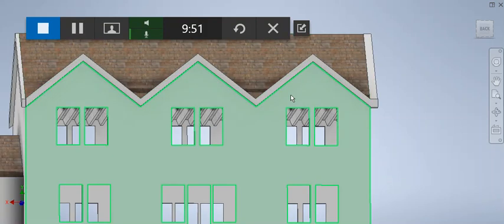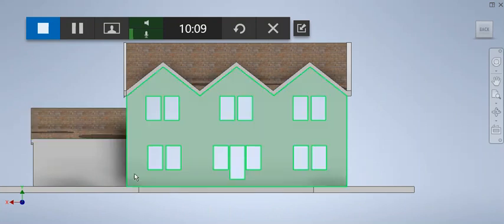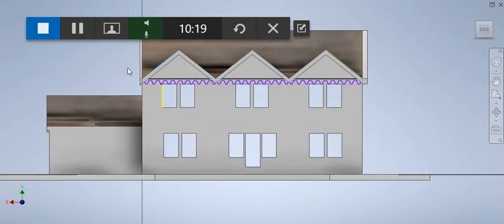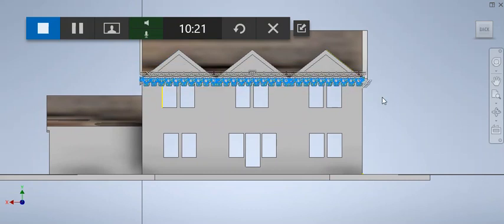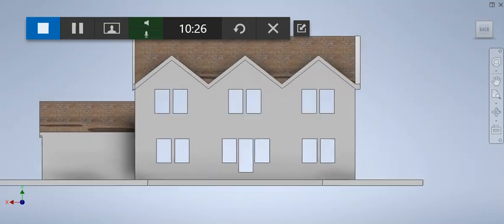So this is the way it looks when you look at it through the window. The ceiling looks this way. And now you're probably wondering if it is possible to copy the same ceiling to the first floor. What I plan to do is simply copy the sketch. I'm going to go back to the previous sketch, select the copy command, Control C, and then finish the sketch.